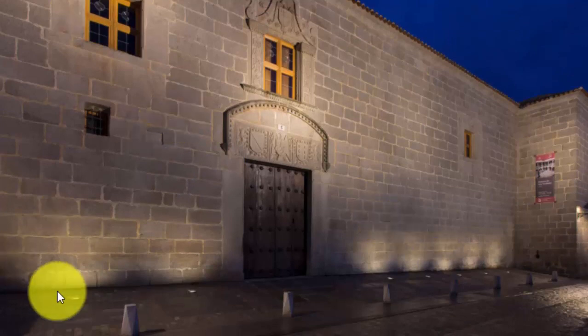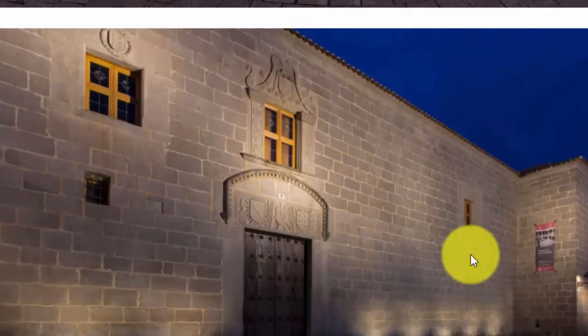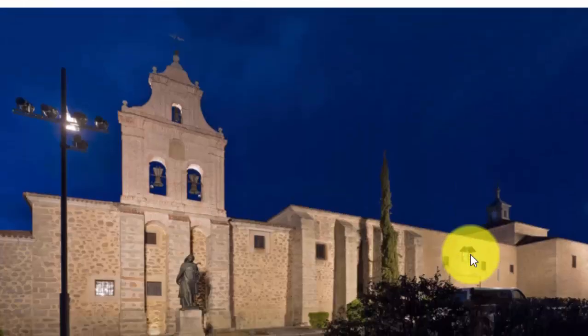And the second thing here is the light fixtures are placed here, uplighting, with, I think, medium optics to make this pattern or graze this wall. And if you observe more, the CCT here seems to be around 4000 Kelvin because the material of the building is grayish, so they have chosen 4000 Kelvin, and it's doing a great job here.